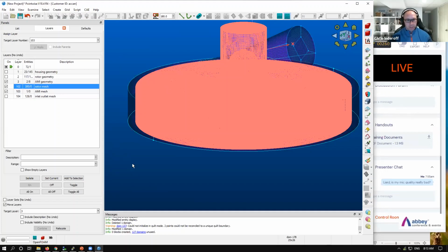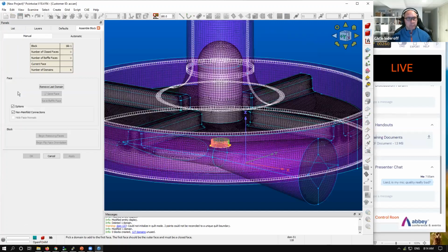So I'm now in my region, at the bottom, and you can see that as it's going along, it's giving us suggestions for what it can assemble next. So I'm just going to go ahead. Oh, so there's the issue. We have this orange region, which is not bound. So what I can do is go and inspect the mesh there, and organize my housing mesh.